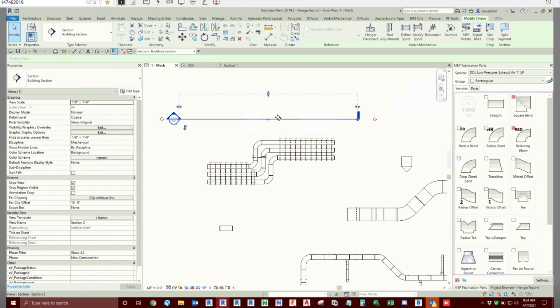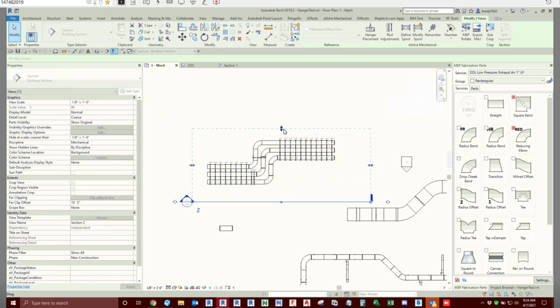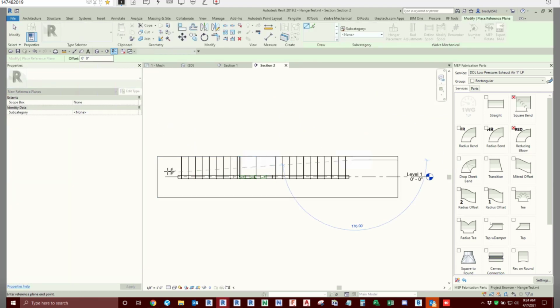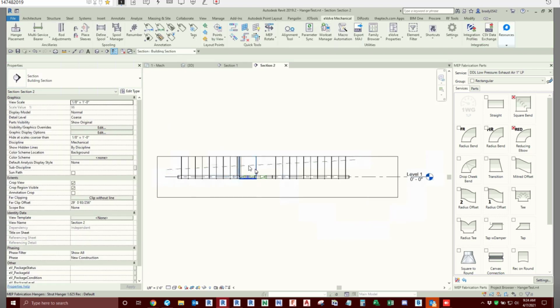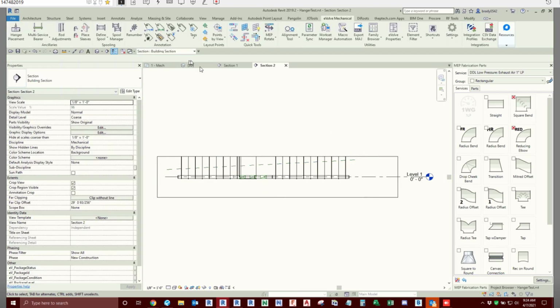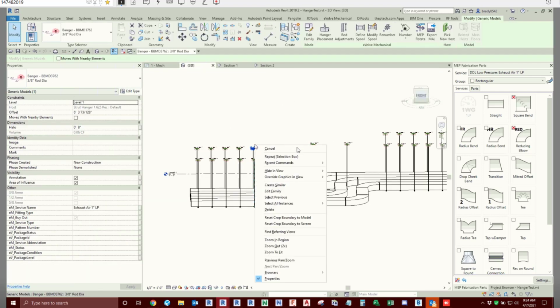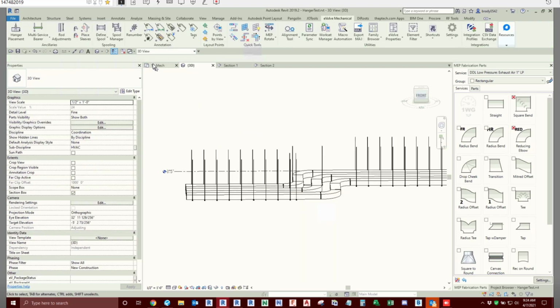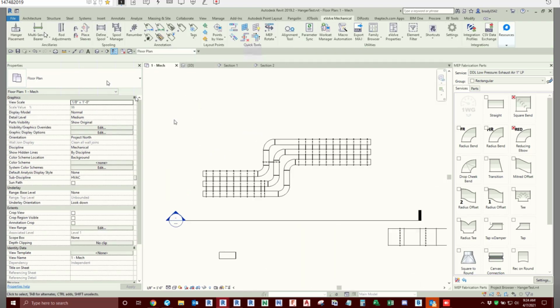So let's make another one going this way, and we can redo that real fast. Go to View, RP, and we'll do a real sharp one here. We'll name this Slope 2. Now in the 3D view, I'm just going to delete all of these, and we'll run our command one more time.